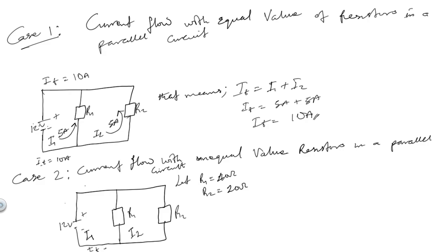Let me explain something before we go further. As you can see, the resistor R1 is greater in value than R2. So current is greater through the path of less resistance. That means much more current will flow in R2 compared to R1, because the resistance R1 offers is greater than that R2 offers to the flow of current. I hope you're understanding. Small values of resistance mean less opposition to the flow of current, and in the same manner, more current will flow in R2 than R1.